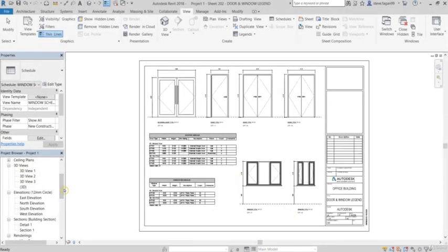So when we're creating our floor plans, our elevations and so on, we create that one single view. Like we have our ground floor plan, that's a view. Everything we do to that view is view specific. So then when we place it onto a sheet, all that information is with that view. So if I wanted to place my ground floor plan that I've placed onto my ground floor sheet, if I try and place it onto, say, the elevation drawing, I can't.